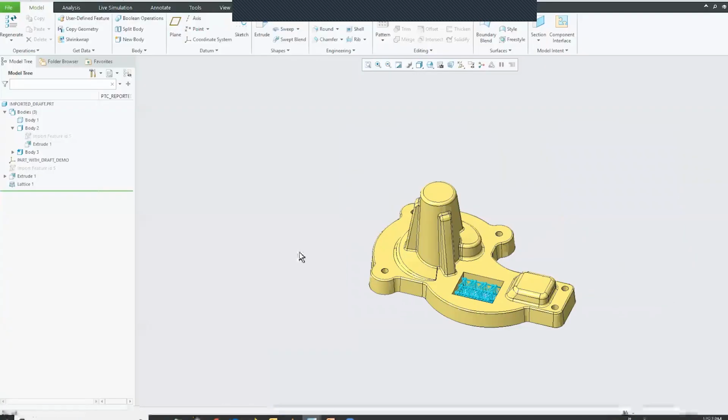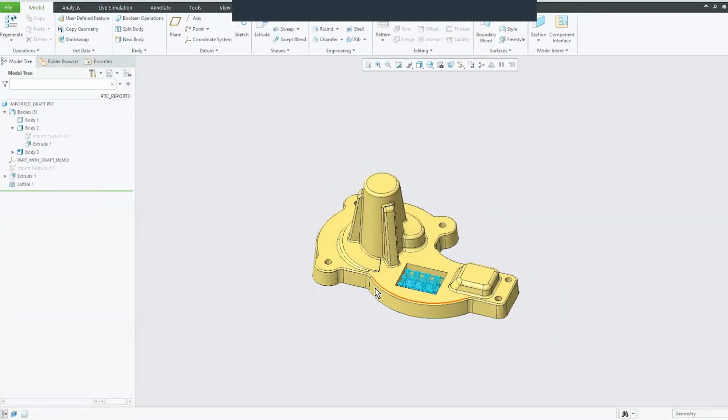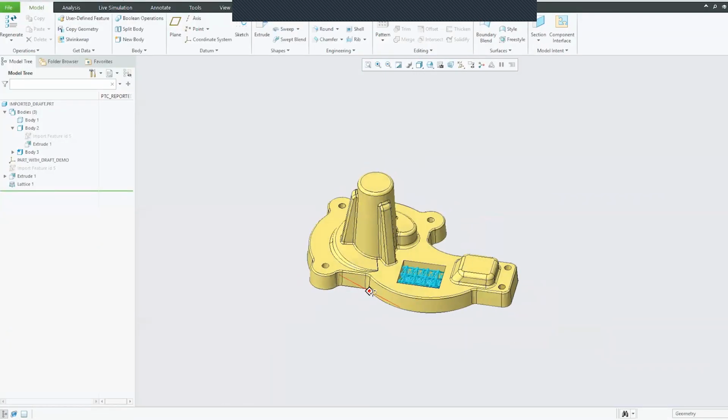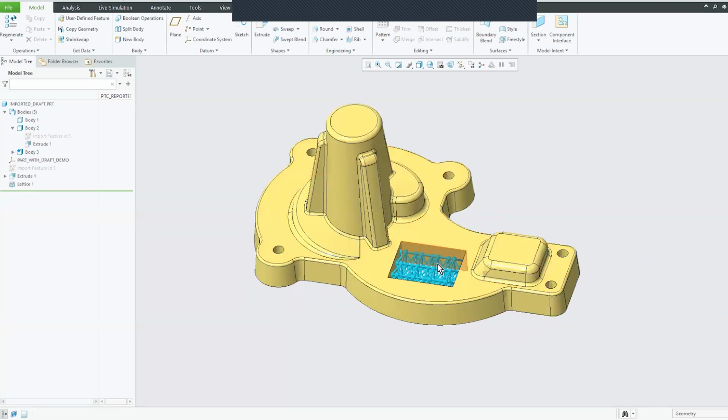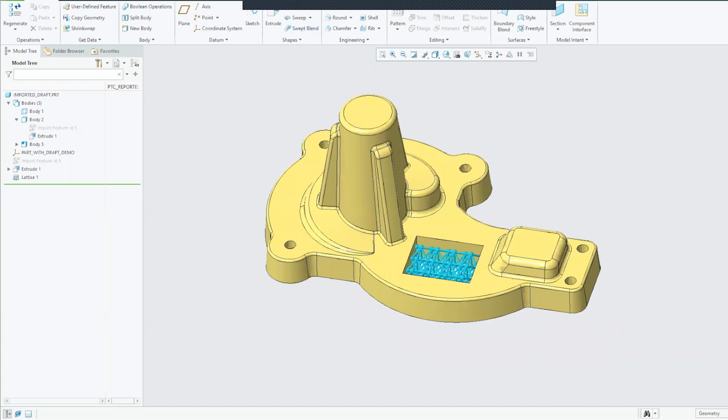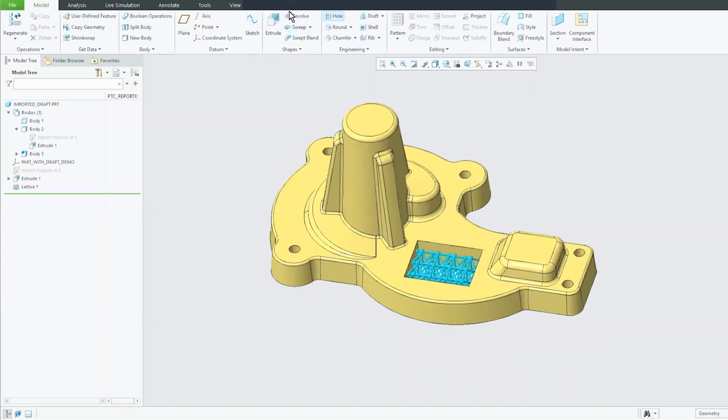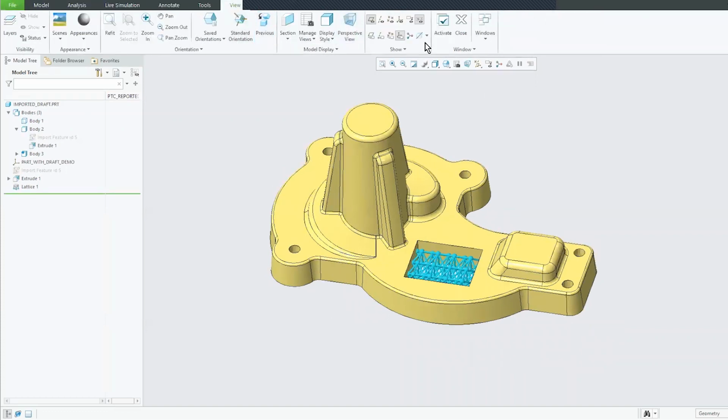We'll call up this part. So here's the part that we were looking at. And one of the things, I have over here a lattice structure, that I was talking about before. So if we go over here and I'll lower my screen a little bit. If we go under view, this is where we can display things. Remember before it was B reps and mixed. In the mixed stuff, I can grab this and fade it out and fade it back.